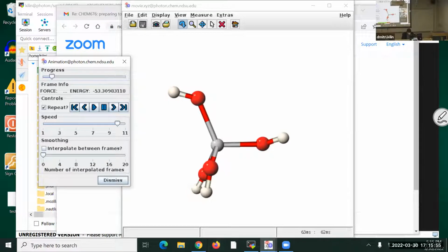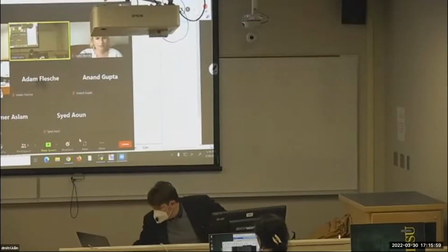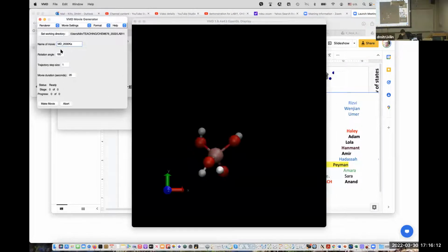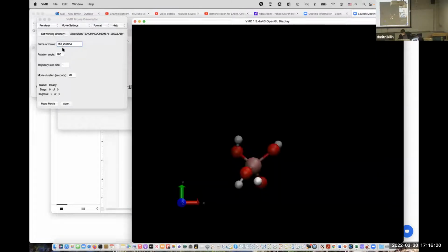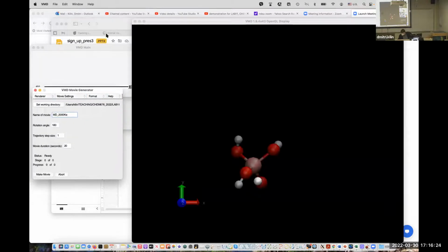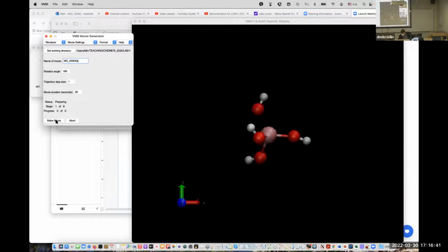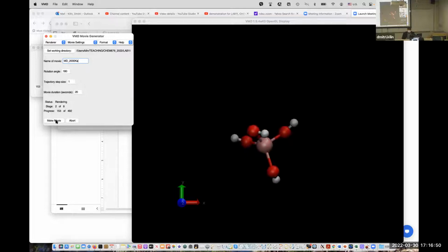The structure. In the VMD, there is a similar procedure which simultaneously creates the file that later can be uploaded to YouTube. So one selects the directory, selects the file name, selects that one needs to visualize the trajectory, and depending on your settings, like I create FFmpeg, but you may do different. And then when you run it, it just goes forward. And as a result, it creates a video file. So I'm just running a little bit ahead of the horse, just showing where we are going to.